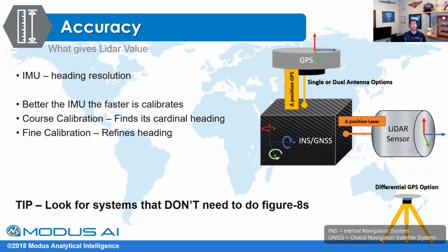What I typically see is someone will buy a brand new unit and fly it by hand, and they won't have good heading control, and they wonder why they're spraying the ground. They see little ripples in their data sets, and it has largely to do with the IMU not being able to catch up with the heading hold equations when figuring out the inertial drifts. Pitch is okay, altitude change is okay, but heading hold seems to be the big thing to look for.